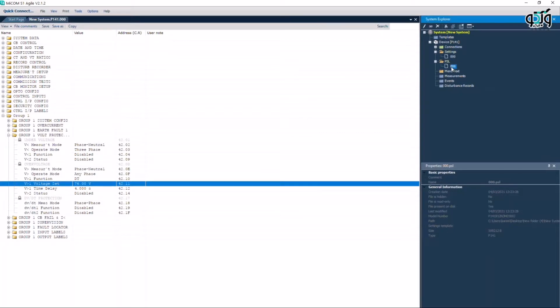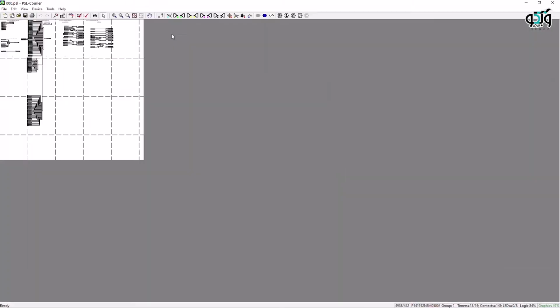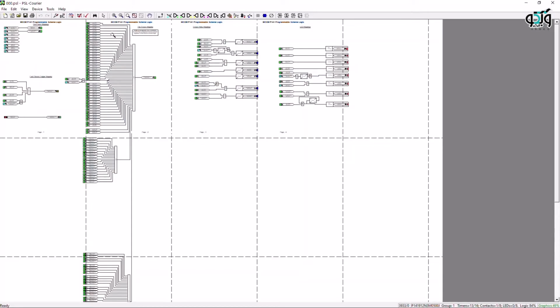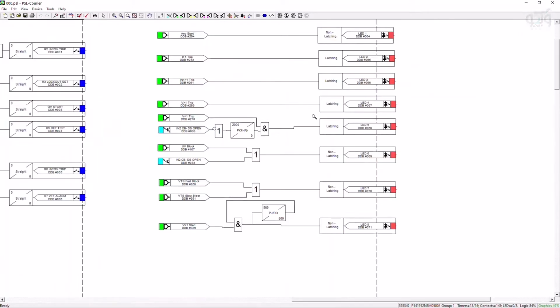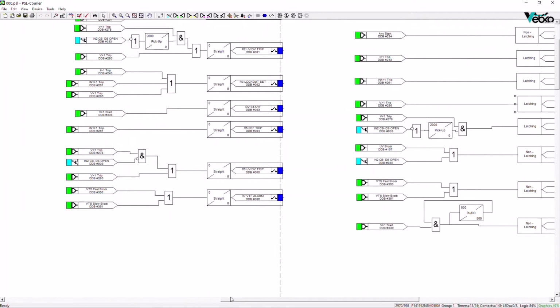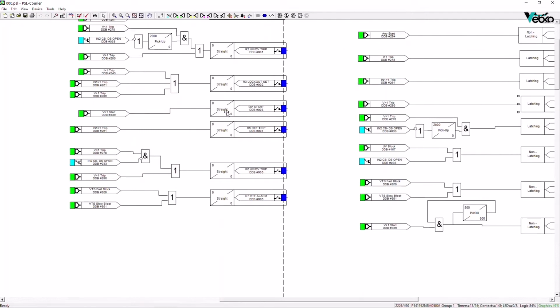After applying the necessary setting in the relay, the configuration is specified as it can be seen. For this purpose, LEDs 1 and 4 of the relay are configured to show the pickup and the trip of this function respectively. In the Output Contacts section, R4 is specified as the contact for recording the pickup. Moreover, R6 output contact in the relay is configured as a trip contact.